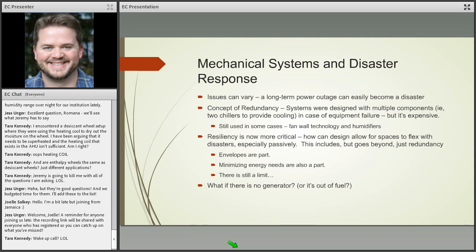And humidifiers are another one where it comes up. This is primarily a maintenance thing, especially for organizations that are in farther north regions. When we lose humidification in the wintertime, that can be really bad news really quickly for some different collection types. And there's a lot of encouragement in terms of installing dual humidifiers, which are a relatively low cost portion of the system, so that if we have a maintenance problem with one, we have a backup that is ready to go online and continue that humidification work in critical collection zones. So that's something to consider.